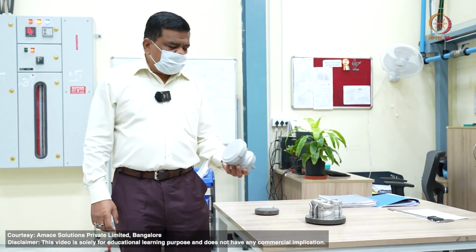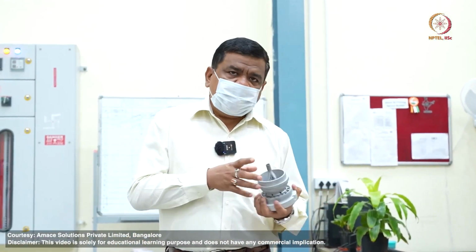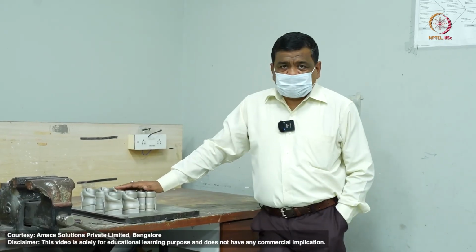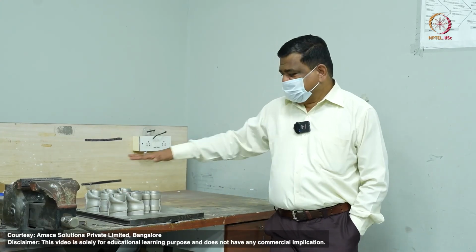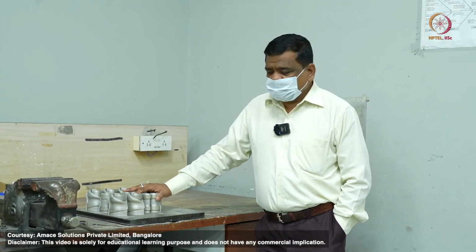So this is also another material. You can see this is very lightweight. This is an aluminum-based alloy which is being 3D printed here at MS Solutions Private Limited. What I mentioned just a few minutes ago, that these laser powder-based fusion processes are used for manufacturing knee implants, and you can see a series of knee implants which are currently being manufactured at MS Solutions.